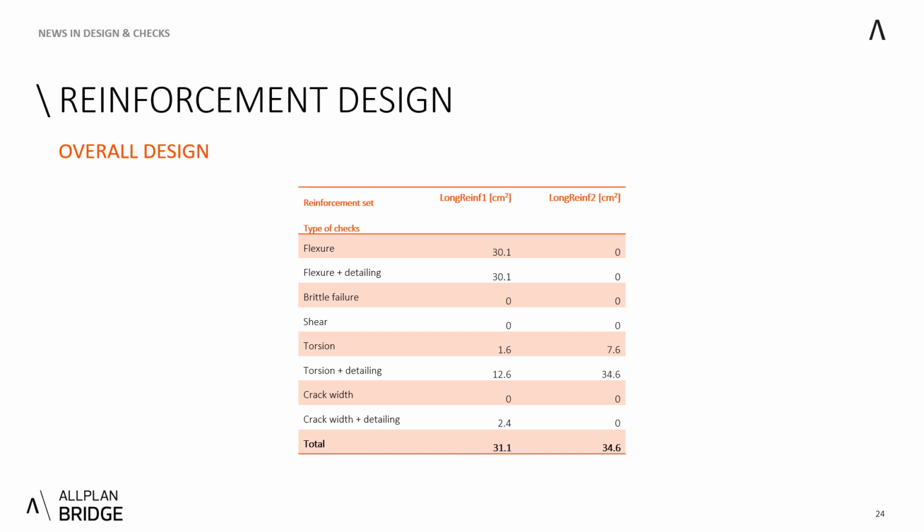And you need to know that this torsion is applied on the already existing flexural reinforcement, and you recalculate this torsion. As I explained, it was this 4.56 centimeters squared. It needs to be added to the already existing flexural reinforcement at the bottom reinforcement set. Therefore, its weight, or the length that it can be filled, is a little bit different.